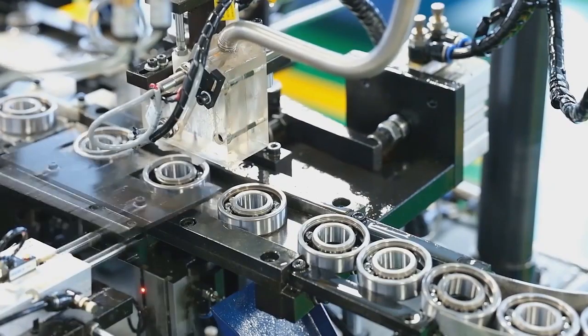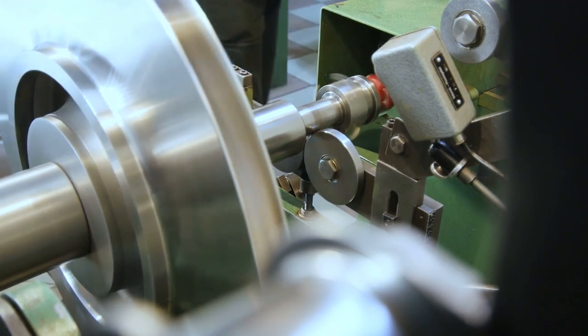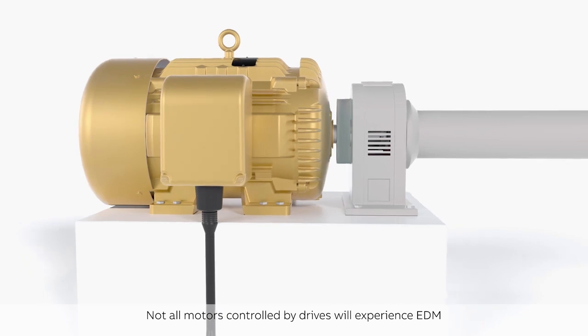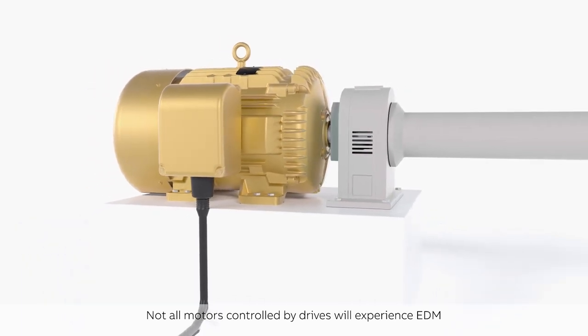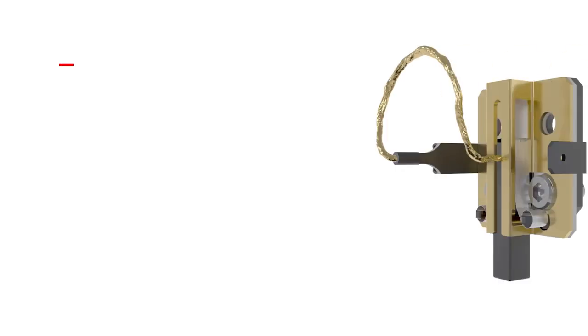Fortunately, there are several practical and easy ways to mitigate shaft current issues. Using proper VFD cables and bearing protection will help protect the life of your motor and driven equipment. Bearing protection from shaft currents can be done in a couple of ways.